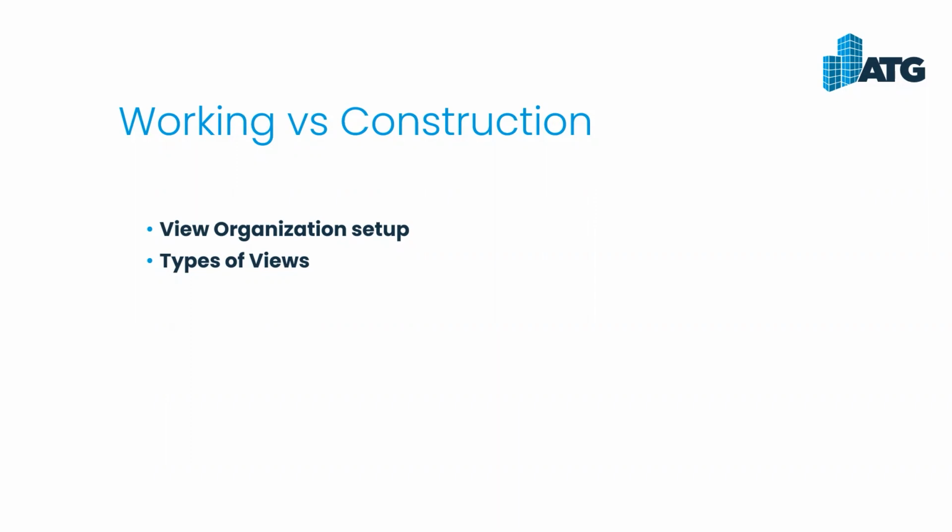So if you're on the MEP side, you're typically getting maybe an architecture model, you're getting a structure model. So you want to bring that information into your project. And with that, you want to go in and set up all of your levels on the MEP side to make sure that they're matching up with the architecture and structure.